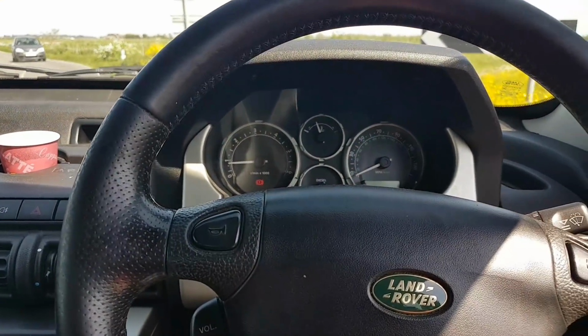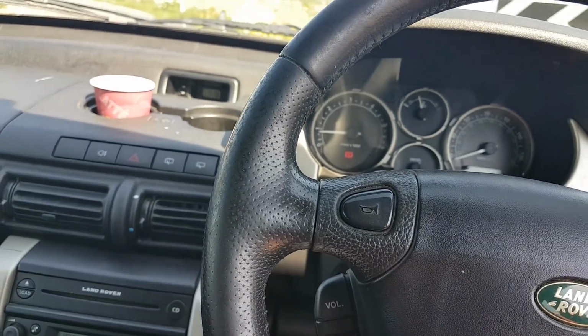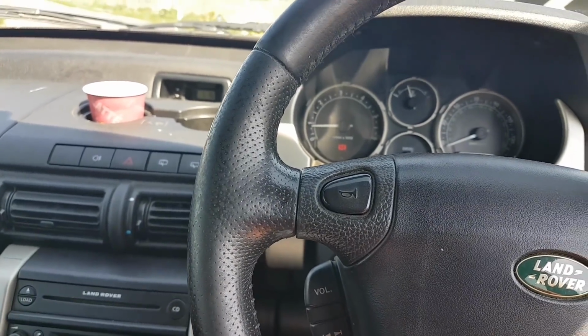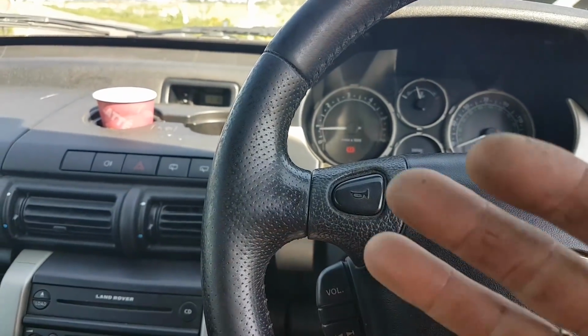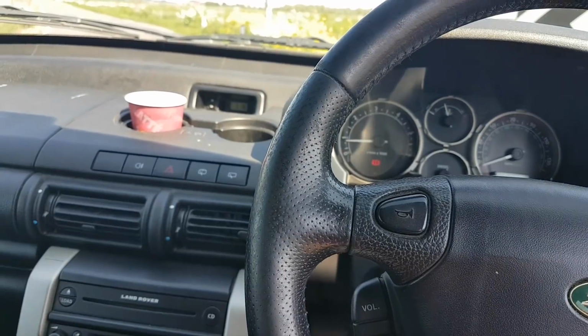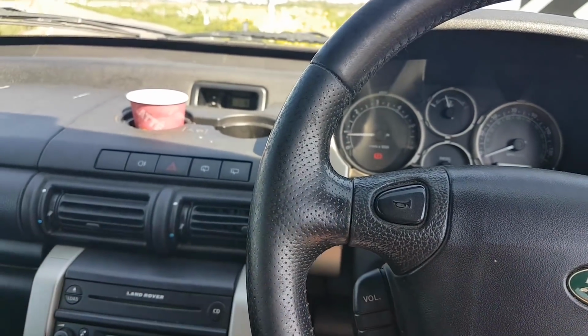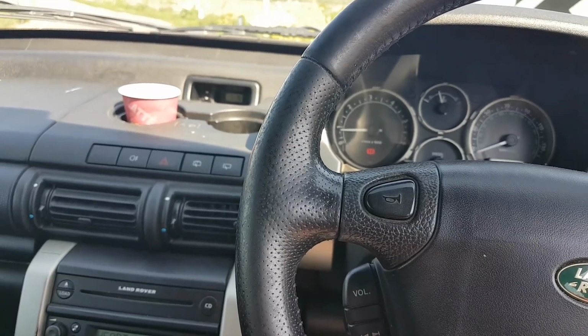Guys, I think that's it for this video, really. If you have one of these, check that first, because that might be your issue. We could have a bad sensor, but I think as soon as we saw those waves, that signal in the scope, that pointed straight away to the pump anyway. That's where the scope can come quite handy.